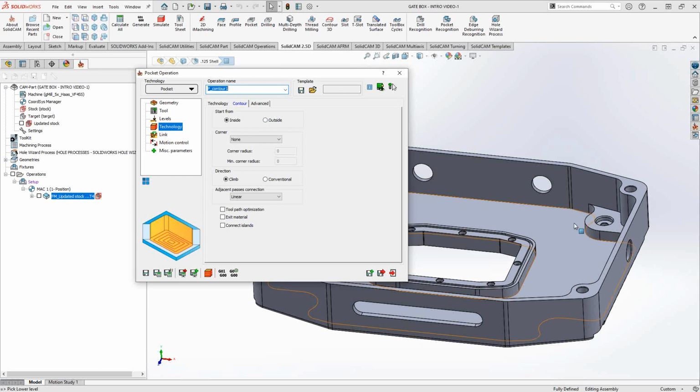If we are doing a geometry that has some 90-degree turns in there, some sharp corners, I can tell it what to do in terms of a corner. So instead of doing a 90-degree turn like you see in the icon there, I can click on fillet. It adds a little bit of fillet in that corner, fillet under your control. I can do a loop, which basically means that in that 90-degree turn, rather than leaving some material right there at that corner, I can loop out, loop back in to eliminate that material. And sharp, basically the same idea, except this time it's just going to jut out, jut back in, and continue.